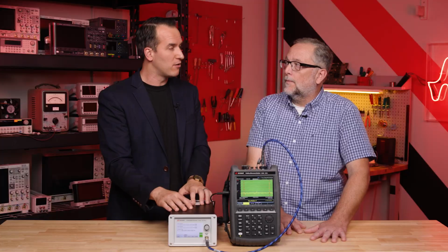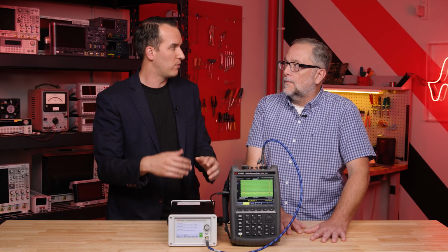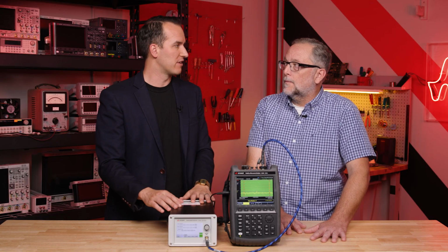Is that typical for an instrument like this, or what's kind of normal for a signal generator? No, it's not. For a typical analog generator like this that you would just use as a general purpose lab instrument, most of those generators, including many of them from Keysight, would typically be able to switch frequencies on the order of 10 milliseconds, single-digit milliseconds, maybe at best 800 microseconds.